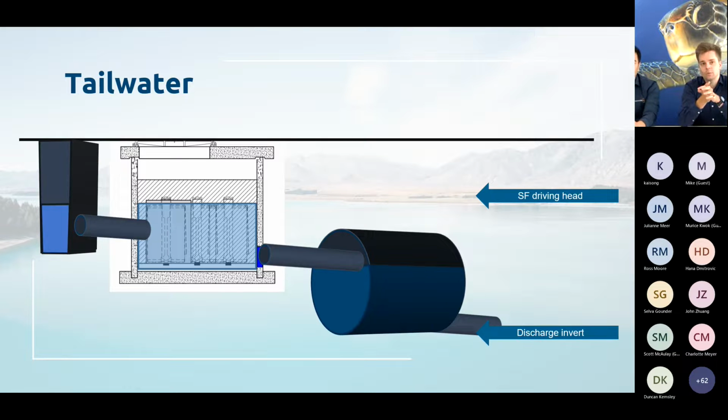There are a number of ways that we can look to make the device shallower to avoid tailwater from a downstream structure. But of course, the moment we bring the device shallower, there's now water that is surcharging the upstream network. So we do have to make sure that if we are raising the device, that we're not going to surcharge upstream, flood a car park, and that we are achieving acceptable depths there.